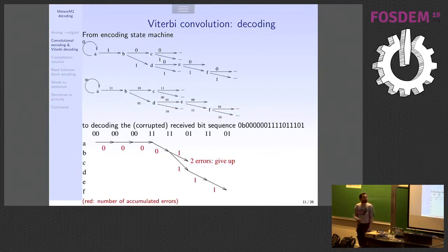In 30 seconds, what you have here is, let's imagine I have received this bit stream. So this is what I have received. So I split what I have received into 0, 0, 0, 0, 0, 0, and so on. And what you see here, I start with 0, 0. OK, I get 0, 0. That is most probably state A with a 0 output. 0, 0, state A, 0, 0. So these 3 zeros are just A looping into the 0, 0.